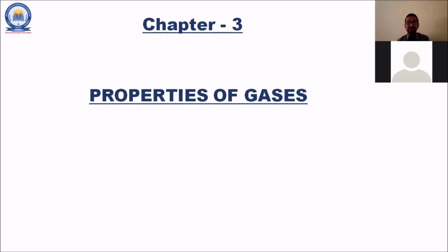So the final answer which we got is W is equal to C ln V2 by V1, where C is the constant. In place of C, we can note down C is equal to P1 V1 or C is equal to MRT1. Also, C is equal to P2 V2, that is also equal to MRT2. So I hope you are remembering all those points.